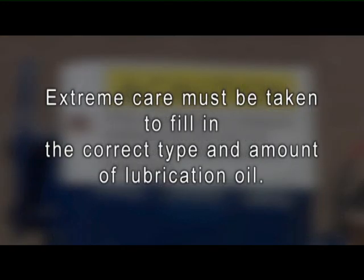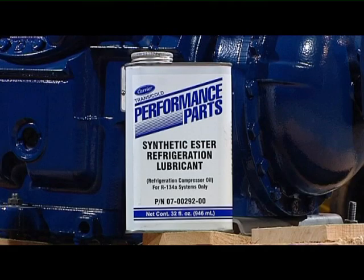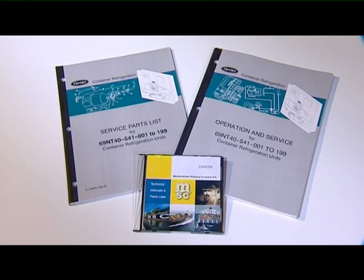Extreme care must be taken to fill in the correct type and amount of lubrication oil. For all types of reefer units, no matter which kind of Freon is being used, you should only use ester synthetic oil. Information on the quantity of oil when filling up can be found in the Carrier Operation and Service Manual.